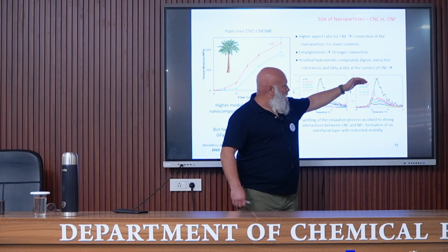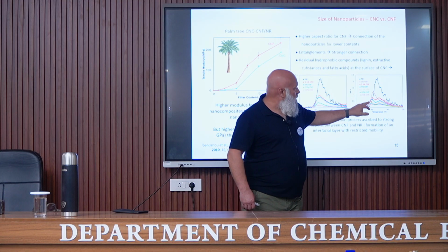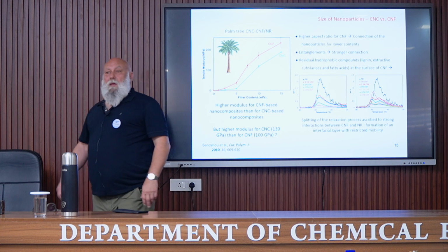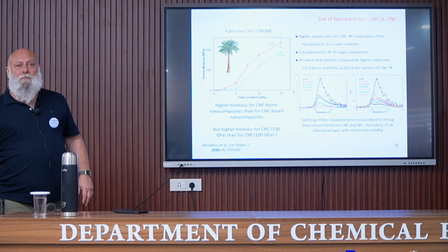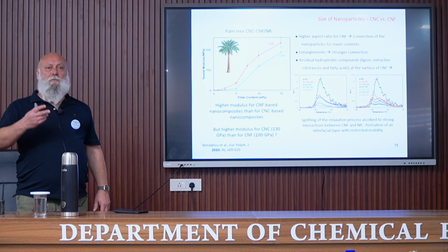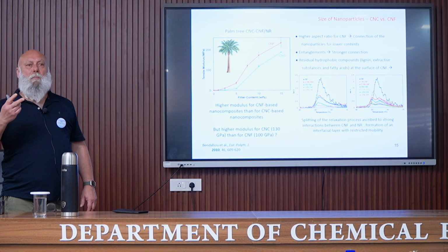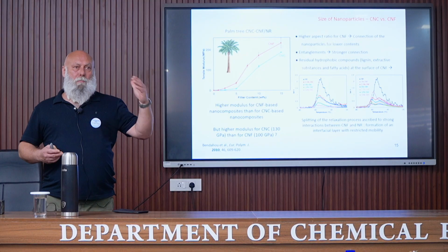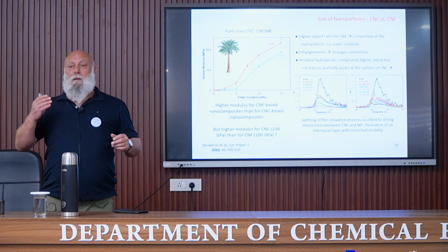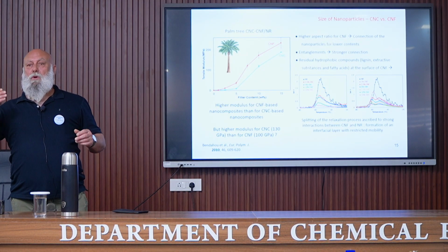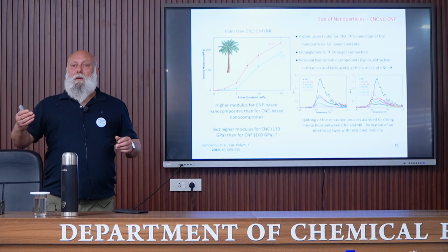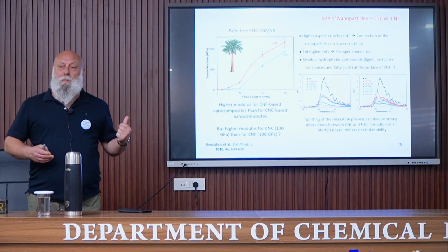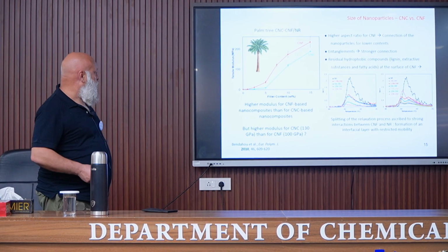Of course, there is a decrease in the magnitude, but we have a splitting into two peaks. This is most probably due to the fact that in the matrix, we have two glass transition temperatures: the Tg corresponding to the bulk matrix and the Tg corresponding to the interface, in which we have stronger interaction because nanofibrils are more hydrophobic.